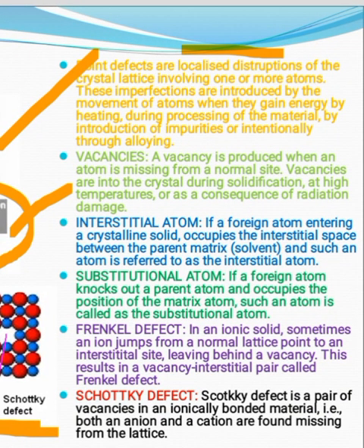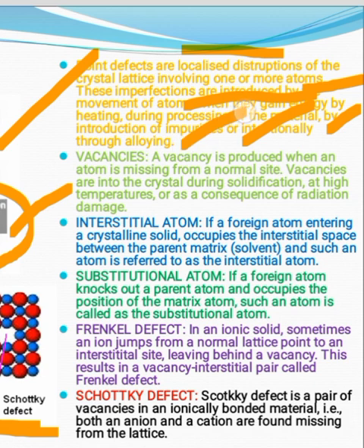The defects are localized disturbances of the crystal lattice involving one or more atoms. These imperfections are introduced by the movement of atoms when they gain energy by heating during the processing of materials. The introduction of impurities is done intentionally through alloying.